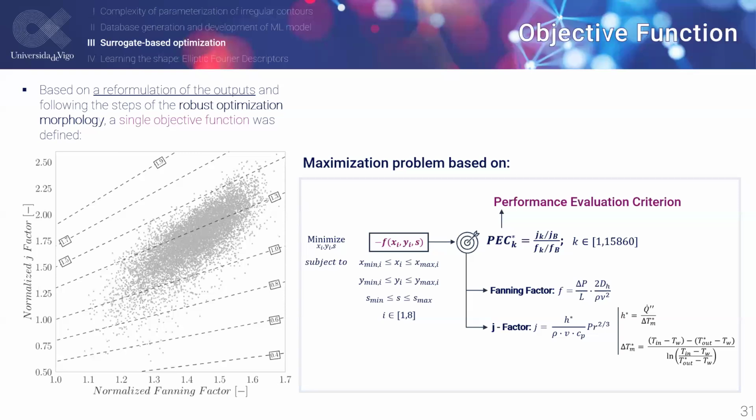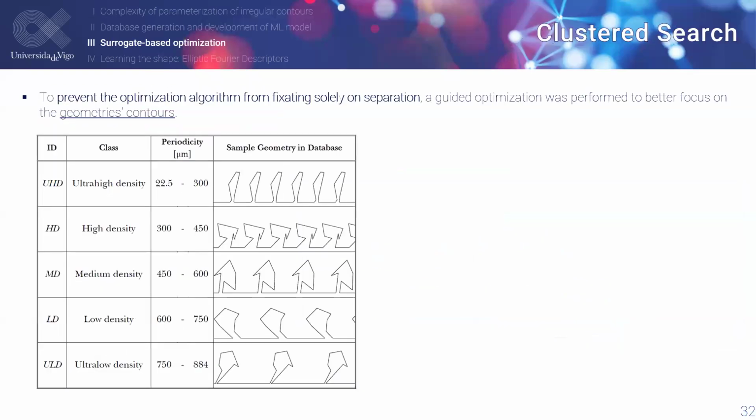In this case, this genetic algorithm was very stubborn. If you're trying to increase the heat transfer capabilities of a microsurface texture and you include the separation between the fins as a target to optimize, the optimizer is really smart. It's going to place fins together and say, now you have more surface, so the heat transfer is going to increase. That's true, but that's not what we wanted.